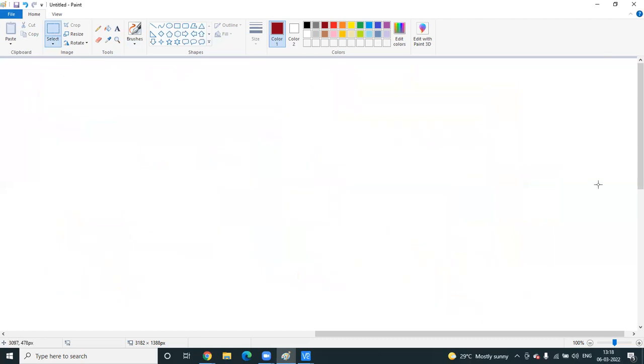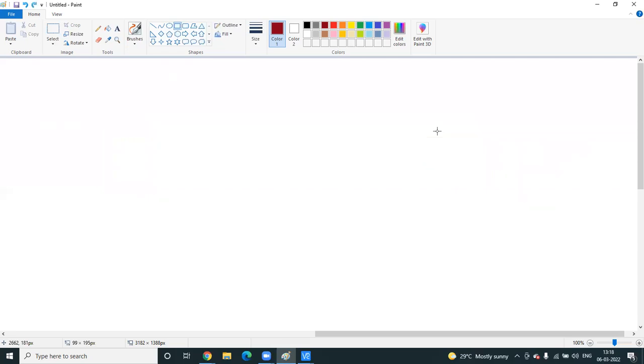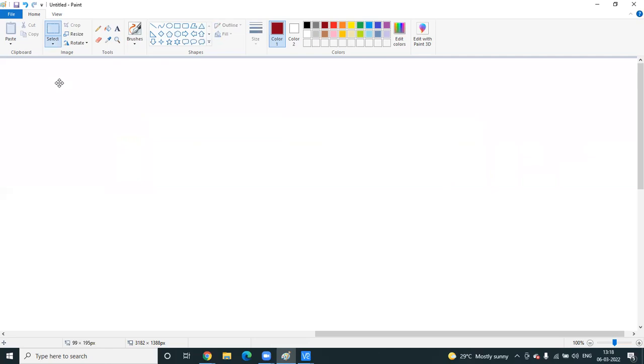Okay, so how to reduce? You can reduce the metal area. This is the first step. Second step, if you are not able to reduce the metal, suppose this is connected to some devices. This is your PMOS. This is fixed. You are not able to reduce. So what will be the next step? How to reduce this antenna error? It is the jumper.